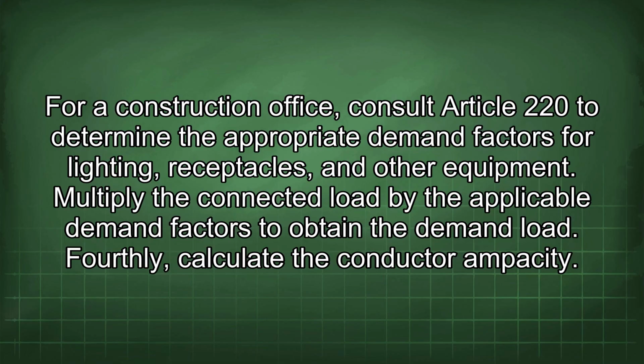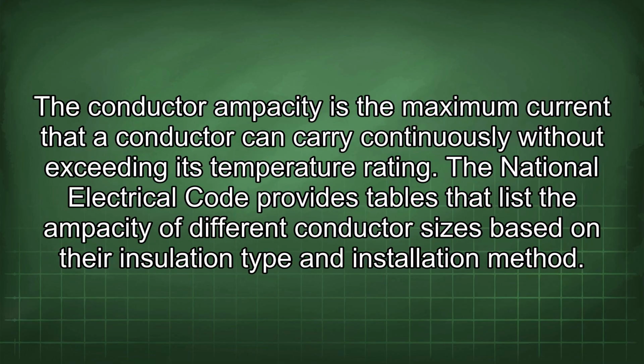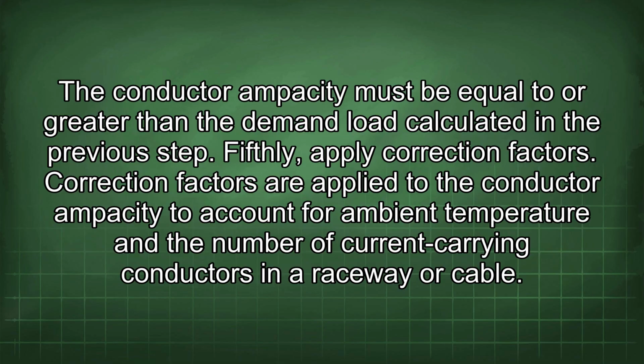Fourthly, calculate the conductor ampacity. The conductor ampacity is the maximum current that a conductor can carry continuously without exceeding its temperature rating. The National Electrical Code provides tables that list the ampacity of different conductor sizes based on their insulation type and installation method. The conductor ampacity must be equal to or greater than the demand load calculated in the previous step.